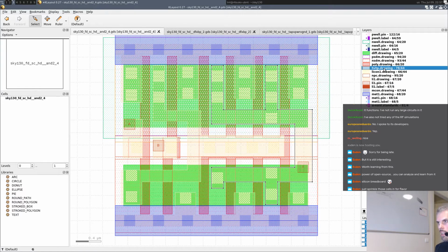And the process has a bunch of different layers that you can use to tweak the characteristics of the MOSFETs that you get, to suit your particular need. Here, at least in the digital cell library, it's pretty much uniform. They all use the same kind of MOSFET. But I imagine there are special implants for high voltage MOSFETs, because you most likely need a thicker gate oxide, I think.